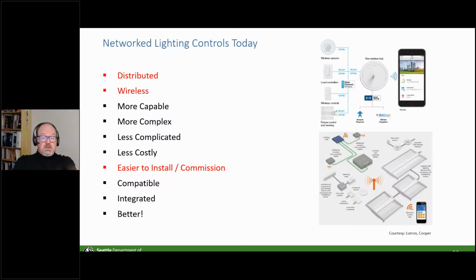In a couple of the classes, if you take a look at some of those resources, I actually detail out some of the costs with respect to retrofit projects. And I give you an example of a retrofit project that I did in my own offices when my offices were in the Bullitt Center. And the retail cost of the equipment for the pretty significant control package that we put together was about 75 cents a square foot. And that was a retail cost, right? That was if I bought all the parts and pieces from Amazon, literally.